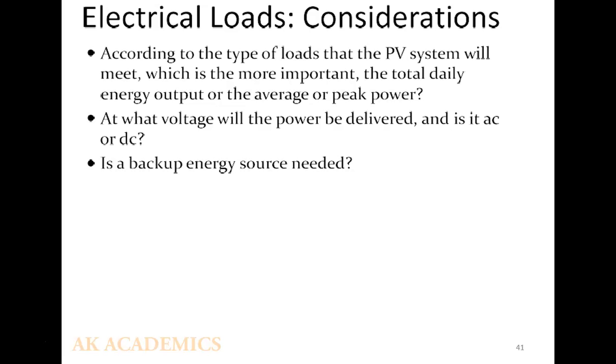And then total energy output would mean, okay, how much energy is this PV able to generate in 24 hours, in 1 hour, in 2 hours, and so on and so forth. So are we going to pay attention to the energy or the power? If you are paying attention to the power, is it going to be average power or the peak power? These are some of the considerations we have to pay attention to when designing a PV system, and all of these are connected to the load that the PV system is going to power or meet.